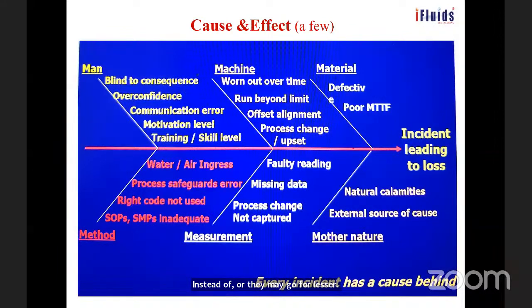Suppose the stipulation is telling 5 chromium, but they may have selected 3 chromium and run the equipment at a temperature identified for 5 chromium. Actually, the material cannot take that much, so it will get damaged. So that's the thing he's talking about.